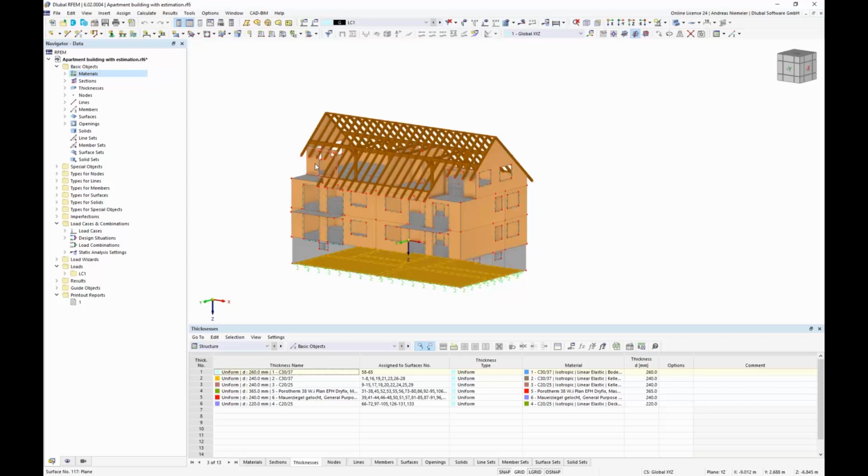In our case, we have the vision that we say, what happens if we let the program decide how the structural system should look like, and that we create the process where you define, for example, the sizes of a hall, maybe length, width, height, and the place of the site, and then the program detects according to the loads on this site on the map or on the earth, for which material, which frames, which distance of frames you need, and gives you finally a complete structural system.